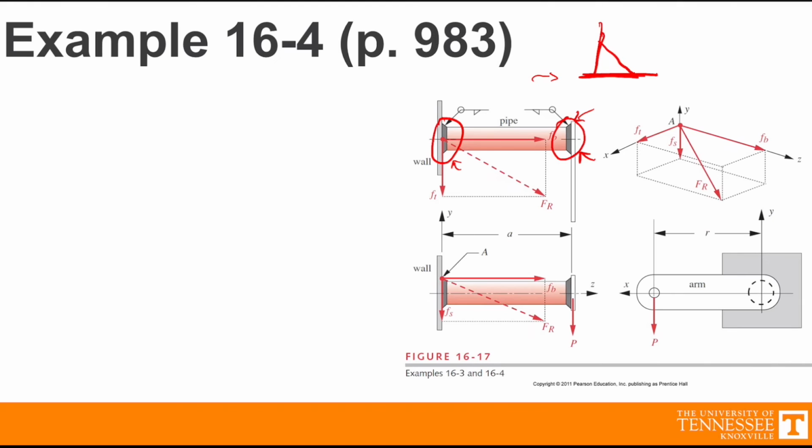We've got the stress due to bending that we have found before, where sigma x is equal to Mc over I. And from that earlier table, we know that M is equal to delta F times A, which is the length of that pipe, times C, which is half the diameter of the pipe, over I. And if you plug all those numbers in, that's going to give us a normal stress of 2,388 psi.